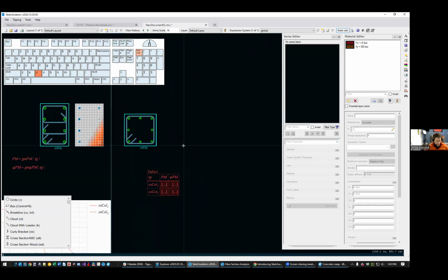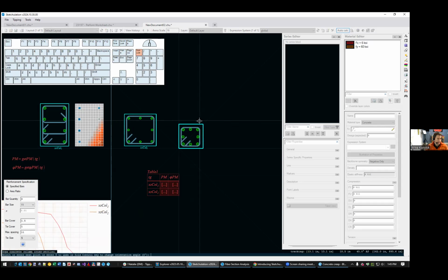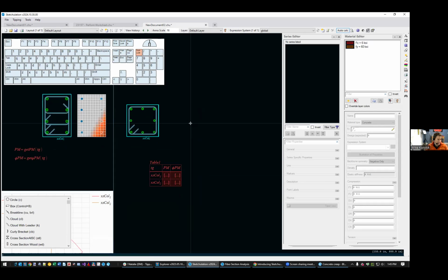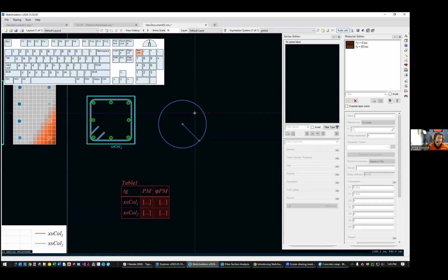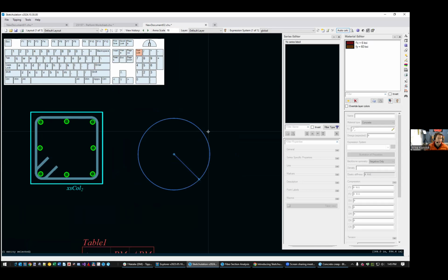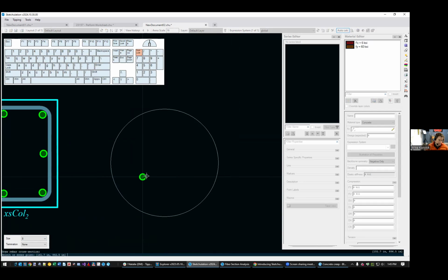And just for fun, maybe I have one more column, ccol. Let's do something fun, like a circular column, and that's an 18 inch round. We don't have a fancy function for that, but I'll make a rebar rbsect. And maybe I'll do number 8 bars just for variety. I put that on, and I'm going to offset it from the edge.